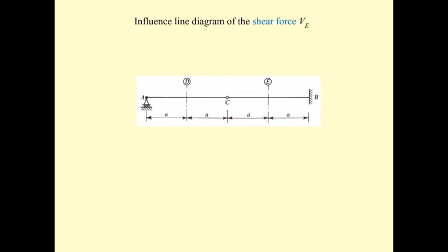And next, we have the shear force at point E. This time, let me have this one. Okay, we're going to put V sub E. Put the roller here, eliminating the resistance to V sub E. And then this is going to be the rigid portion of the beam, because it's fixed here. When you apply the force, this is downward, this is upward, in which this is still hinge and this is still roller. What happened is this is rigid. Again, there is no movement.